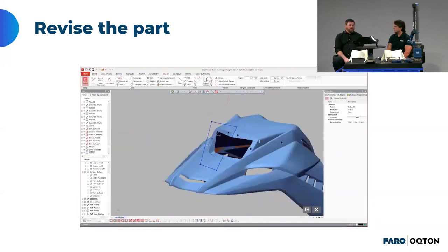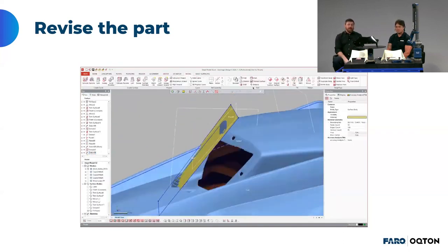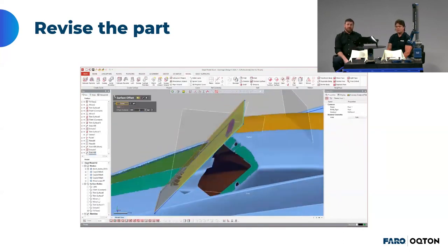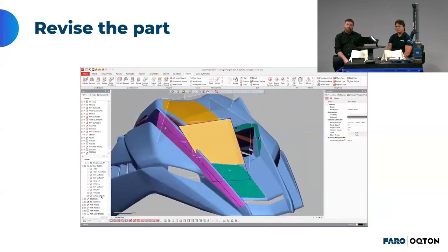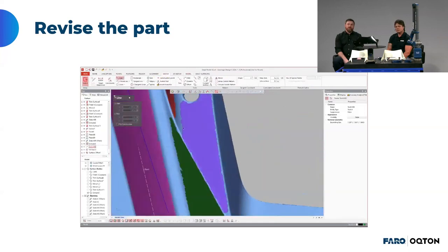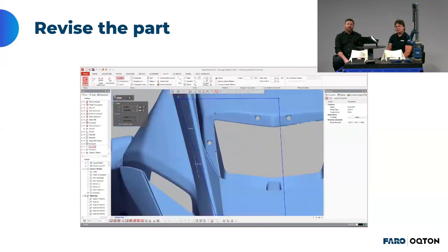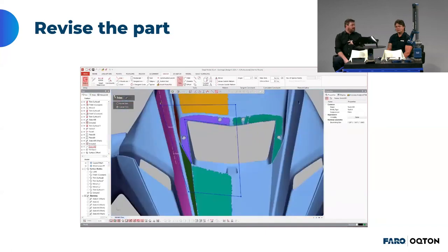You can reverse engineer the part itself, or I'm designing around the mesh itself here, as you'll see as the video progresses. So I'm using a lot of the same tools, but we are doing the design of the replacement part inside of Design X. And you see I'm doing lots of surface drawing and fitting directly to the part, but I'm not reverse engineering the scan itself.